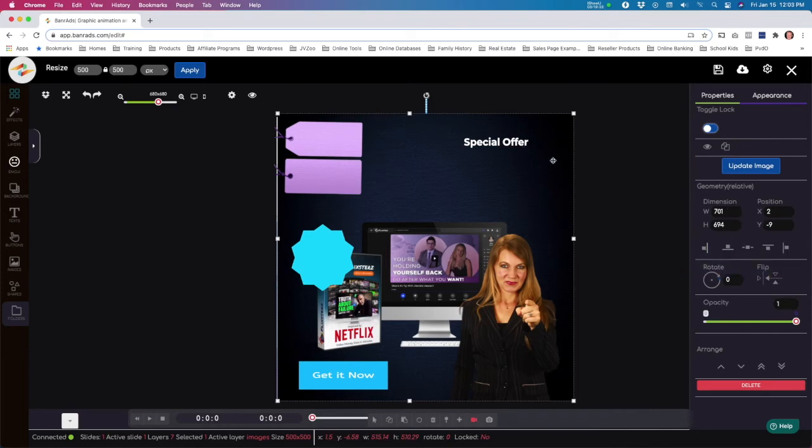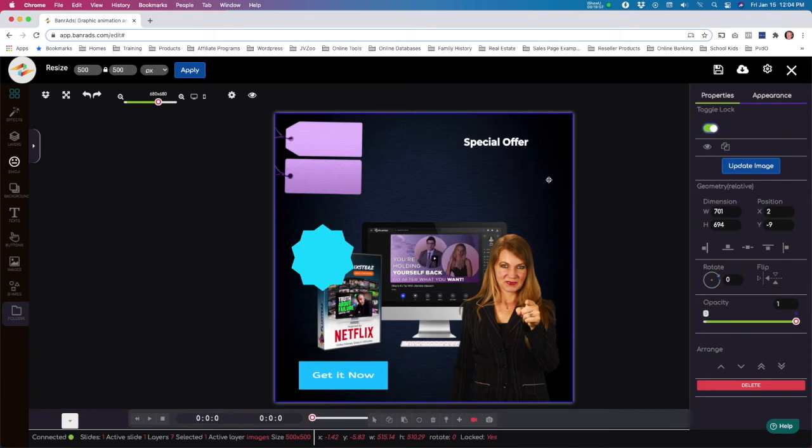If you want to have a certain dimension done manually, in this case I'm selecting the background, I can do that here, also with the position, and I can show it or not show it. I can copy it here, I can toggle it, lock it. In this case, then I cannot move it anymore, which for a background in this case, I would prefer.